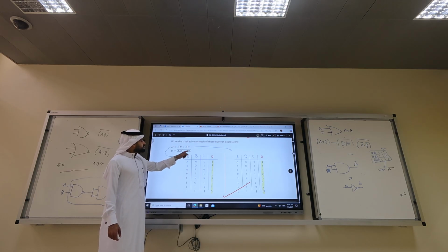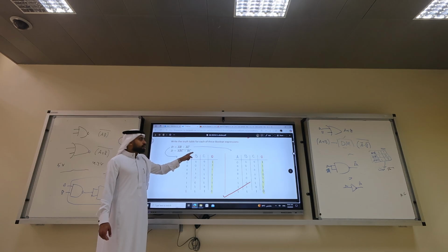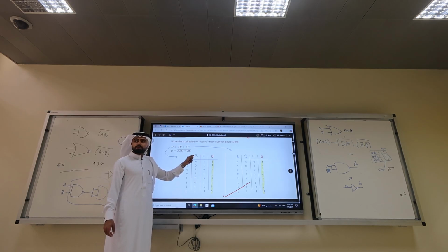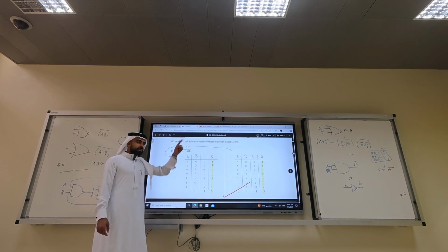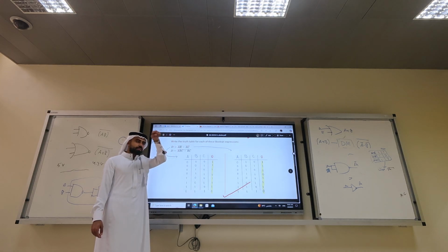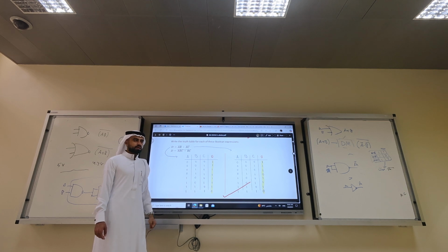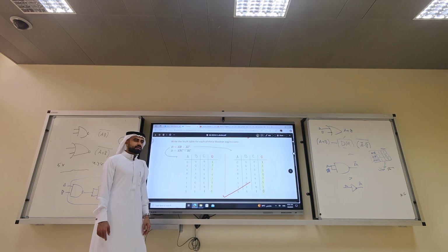As a matter of fact, you can simplify this expression. What is ABC plus BC? It's A plus BC. A and BC. It is ABC. Oh, BC. Take BC and with A plus 1. Yes, sure. So A ORed with 1 is A. So it will be ABC. No, A ORed with 1 is 1. Yes. Okay, you're right. My bad. So it will be BC.